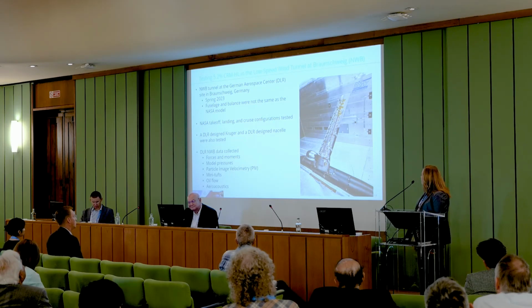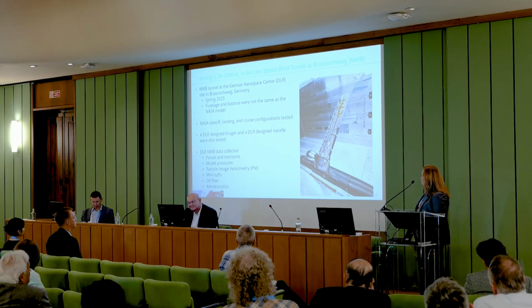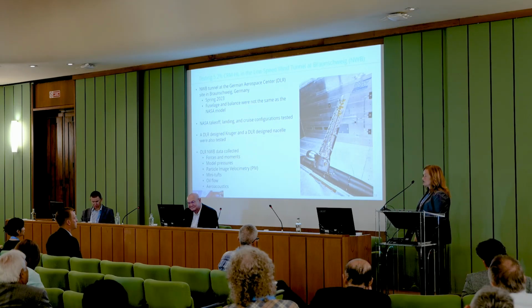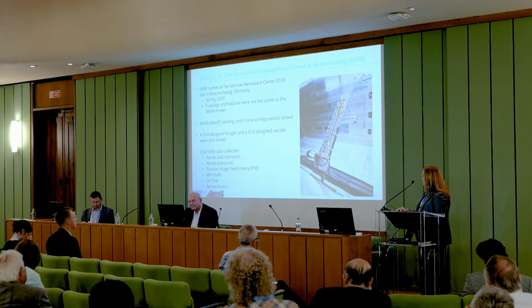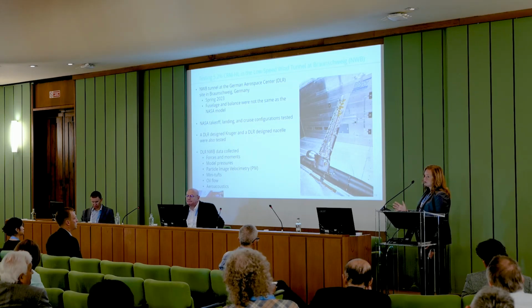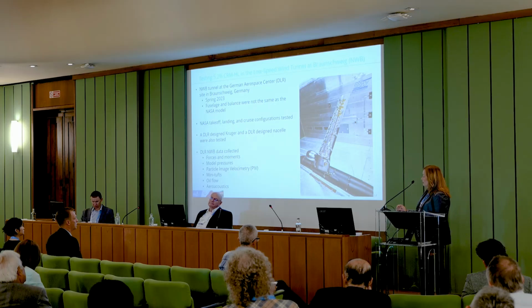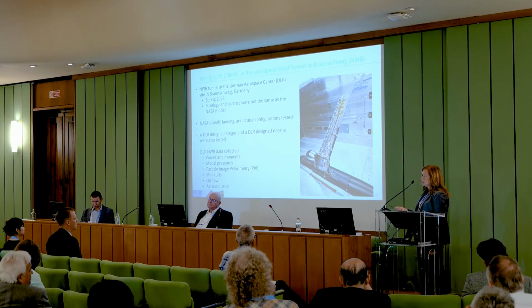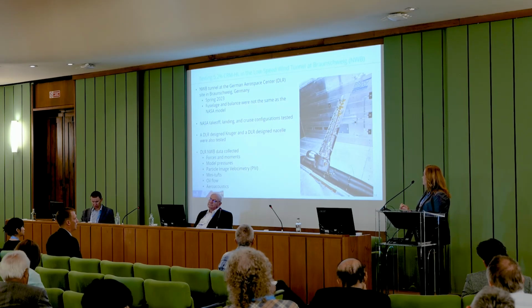We tested this model at DLR in Braunschweig in the spring of 2023. I will mention that the fuselage was not the same as the NTF model, and the balance, it was a different balance that was used. Another thing that I'll go ahead and point out is on these semi-span models, we have to use what we call a standoff. And this standoff height for the 14 by 22 test, the DLR test, and for the NTF test were all different heights.